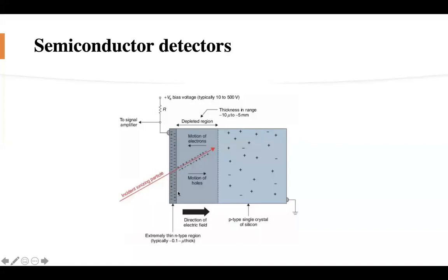When the detector is hit by radiation, it will create ion pairs in the same manner as the gas detector mechanism. As this charge is produced and there's applied voltage, it will collect the charge and produce an electrical signal. The electrical signal links to the deposited energy in this area. This is how it works.